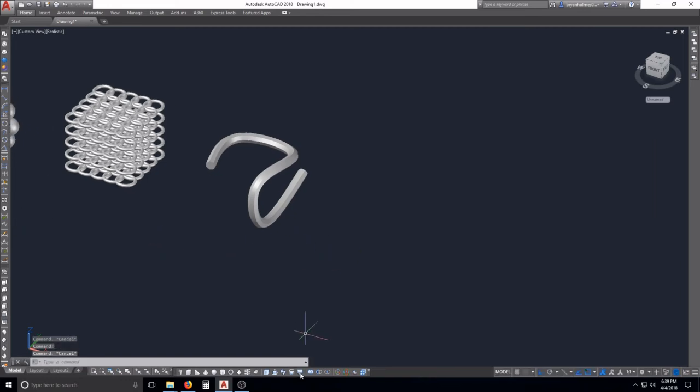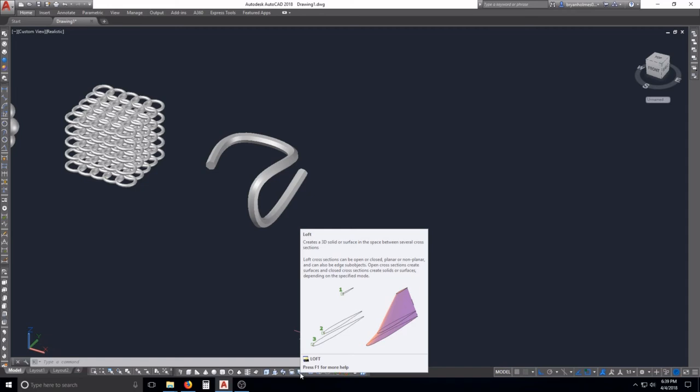If you remember from looking at it earlier, it takes 2D shapes and 2D wireframe shapes, which are on different XYZ points, and it connects them. See how in the pink there, the 2D wireframe, I can't really move my mouse or it'll go away. The first point, the second point, and the third point are on different Z-axis planes and slightly different X and Y locations as well, and you result in that shape you see in pink there to the right. So let's try this out.